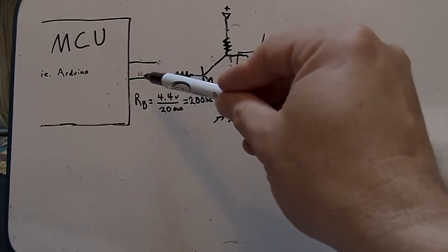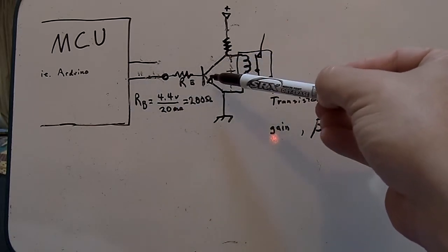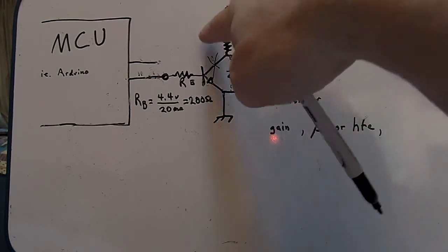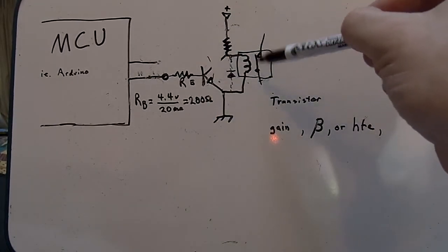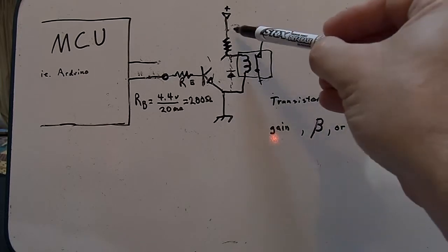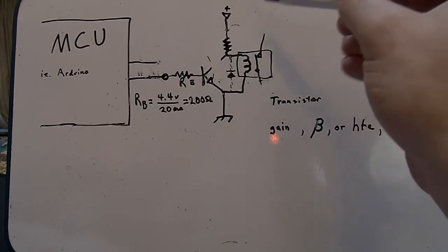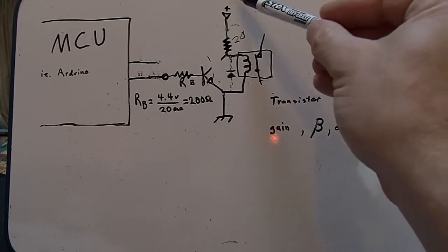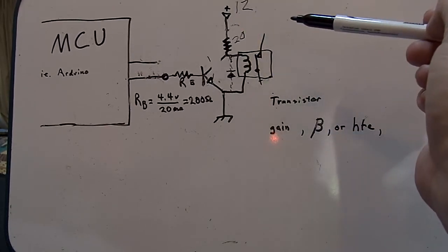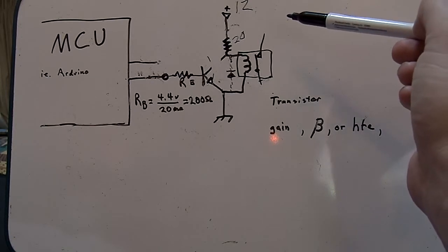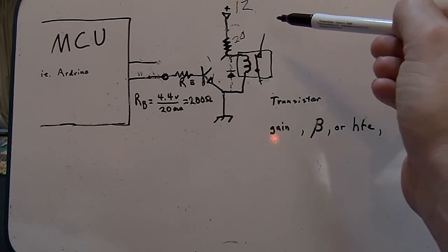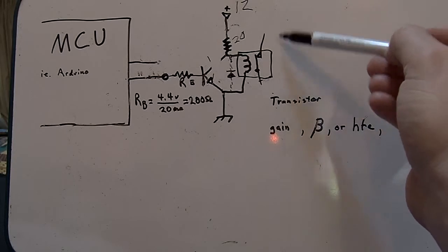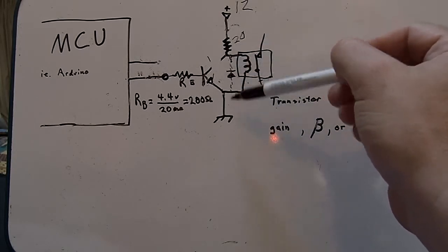When this transistor is open, say this is a low, the transistor is off, then this is basically disconnected now, and this resistor in series with this relay, we turn the relay on. So you'd have to choose a resistor that's small enough where it wouldn't interfere with the relay turning on. So maybe this would be something really low, maybe like a 20 ohm resistor. Maybe this is a 12 volt circuit out here. So what, 60 milliamps? Might be enough to turn on a fairly heavy relay. And again, you can have your snubber diode in there if you want.